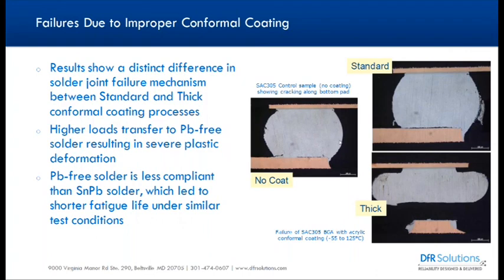The reason we put underfill underneath components a lot of times is because we want to mitigate the effects of shock and vibe. So we're kind of holding the components in place so they don't break. But we usually have a trade-off between shock and vibe and temperature cycling. If you're doing a conformal coat, you're basically preventing humidity effects. You're not doing anything for temperature cycling, as you can see in the current slide, and you didn't underfill it, so you're not actually mitigating. So it's the thought process of trying to use conformal coat as an underfill or accidentally getting conformal coat as an underfill. That's the real problem. If you use conformal coat correctly, no problem.